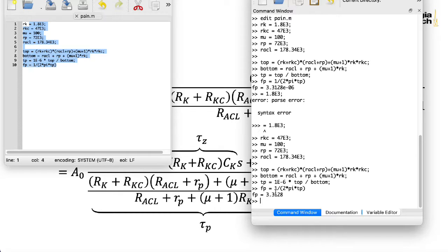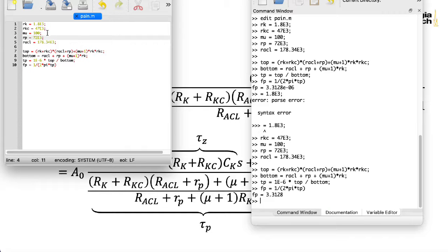Now the pole frequency should be higher than the zero frequency. So to confirm that, I would probably want to go back and do a more careful job of computing the zero frequency. That would be a good sanity check, but I don't feel like bothering because this case isn't very interesting anyway. Okay, so what about the pole location for the higher gain setting?